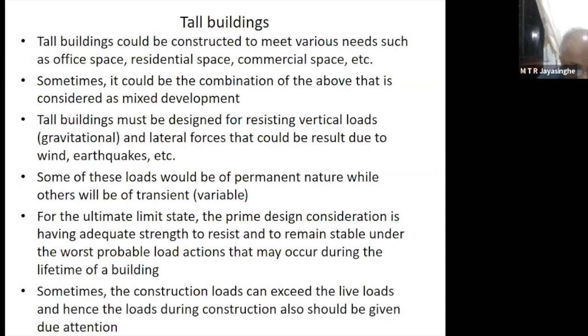Not only the project management part, but the quality assurance scheme should be very accurate at the site. And you can't afford to have any leaks in the shutters. You can't afford to have a situation where you ignore curing of the slabs. The curing of the slabs will be very important, at least for 7 days, because we are using cement with a lot of tricalcium silicate.